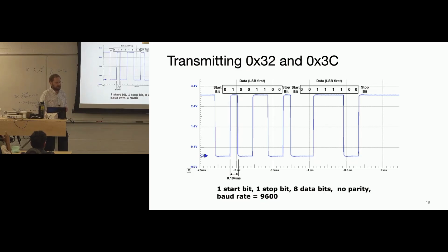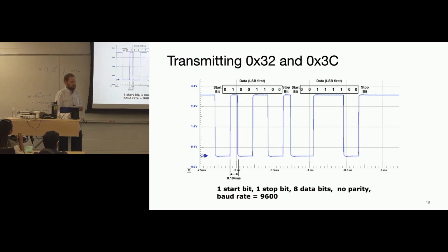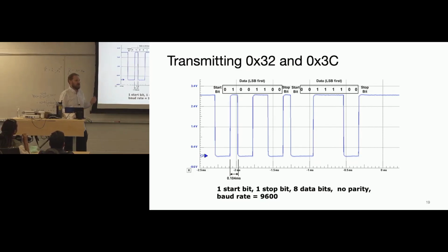You're technically still relying on a clock signal. That's just internal. Correct, it's not coming in from the outside. Right, but the problem is you have to synchronize there. And this is always a perennial problem: you're trying to synchronize between clock domains. If you're off by a little, bad things happen. So you need a resynchronizer, which is essentially the structure we just showed you by oversampling.